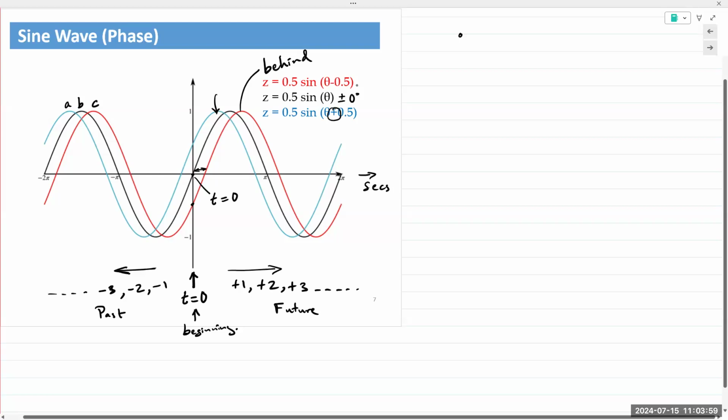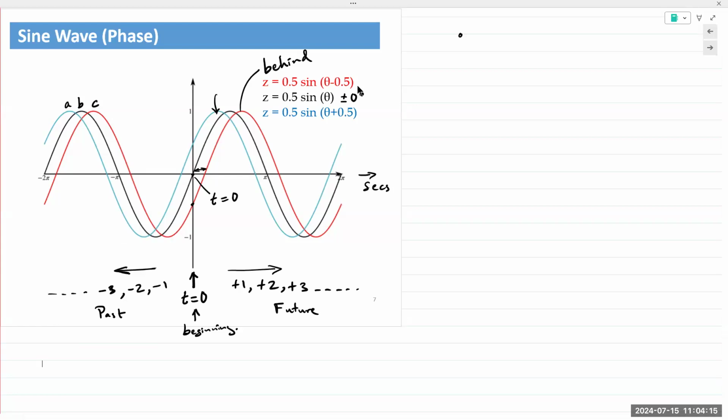And so we note that with a positive phase angle. So even though it falls on the negative side, we note it with a positive phase. So if the waveform is ahead, it is positive. If the waveform is behind, it is negative. And that is the mathematical notation for these two waveforms.